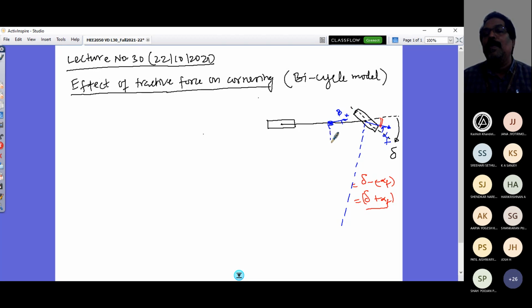So if I draw a perpendicular from there, and that would meet, I'm just bringing in, I draw this deliberately with a bigger angle so that I can confine this point in my screen. If you look at this, the turning is on a 30 meter road, I cannot accommodate that here. So that is broken here, that's broken here, and it is meeting here like that, you can see. So to bring it in here, I take these angles, whatever I'm representing, as larger angles, but they are very small angles. So cos of that angle is 1 and sine of that angle is the angle. That we are already aware of.